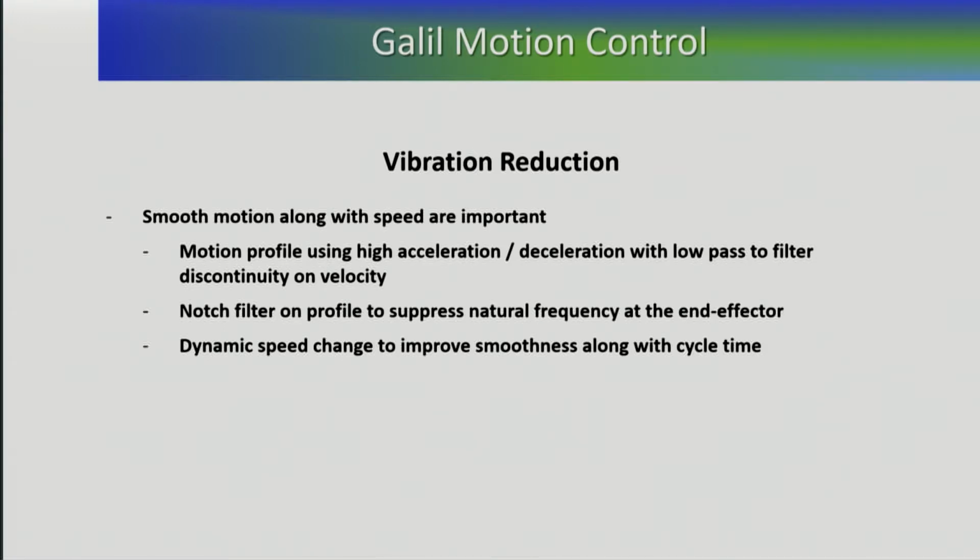The controller, the digital filter, gives you the ability to take that information, and depending on where those frequencies or frequency is located, you can apply a notch, or if it's high enough, just apply the pole so that you're able to still maintain a good system bandwidth and responsiveness and eliminate the potential risk of that vibration in the system. That again is an assumption that you're able to see it and the control output is able to filter that out.